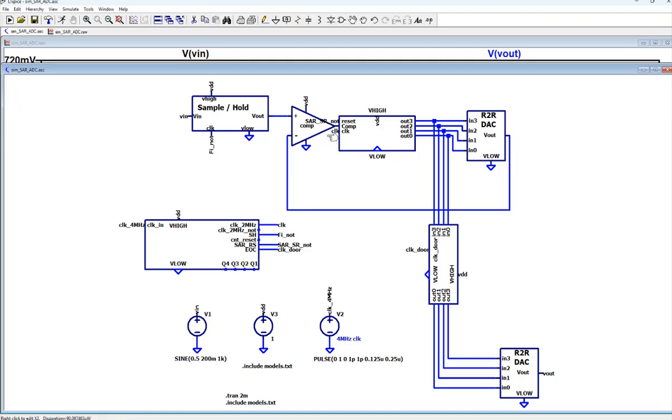Is there any control in between here? No, it's just an op-amp, a comparator, right? And the result here is from the previous state, from after the DAC. So you have the SAR's output, and it's being converted back to analog voltage and sent back for the comparison, right? There's no control over it. I don't have any latches in the middle. So whenever you have a voltage here,